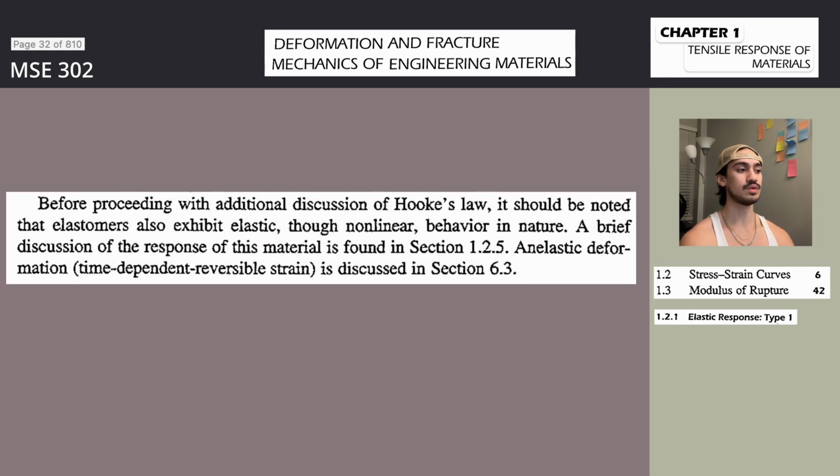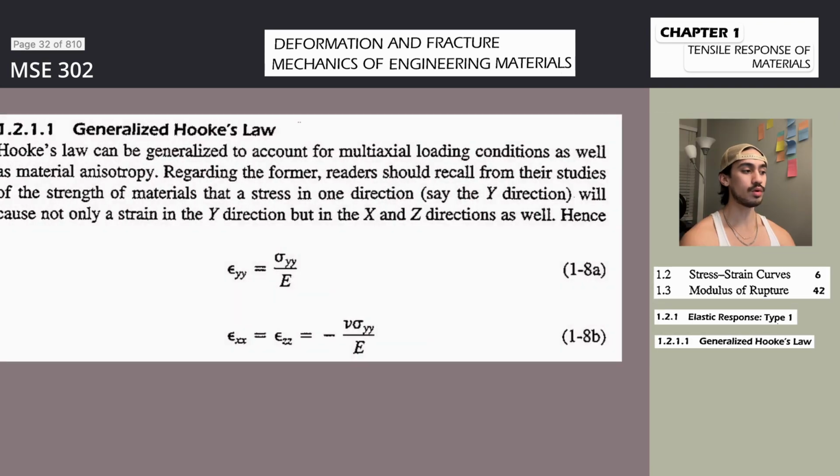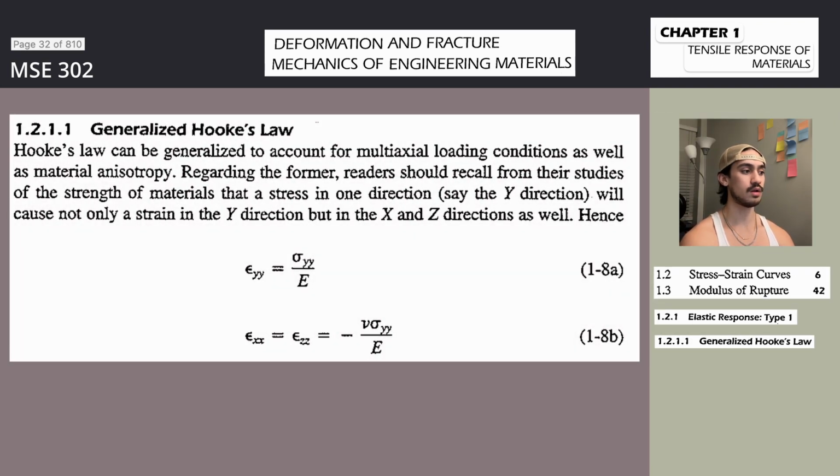1.2.2 Elastic homogeneous plastic response, type 2. When a material has the capacity for plastic deformation, irreversible flow, the stress-strain curve often assumes the shape of curve 2, figure 1.2. Here we see the same elastic region at small strains, but now find a smooth parabolic portion of the curve, which is associated with homogeneous plastic deformation processes, such as the irreversible movement of dislocations in metals, ceramics, and crystalline polymers, and a number of possible deformation mechanisms in amorphous polymers.